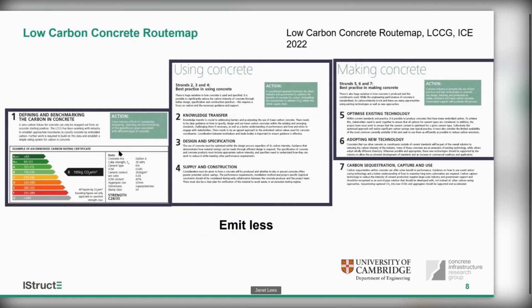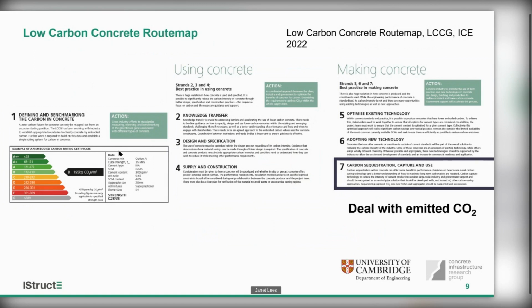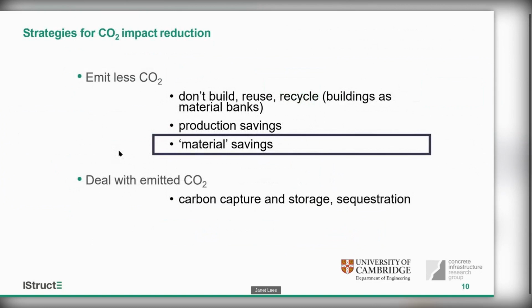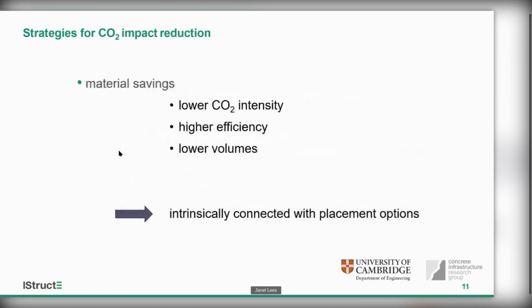If I look at another example of the low carbon concrete route map published through the ICE, then again, the defining and benchmarking, the using concrete terms and aspects of making concrete are about emitting less, and the sequestration, capture and use is about dealing with CO2. So within that framework, the particular strand I'd like to pick up on for the rest of the talk is in the category of emit less CO2, and in particular material savings.